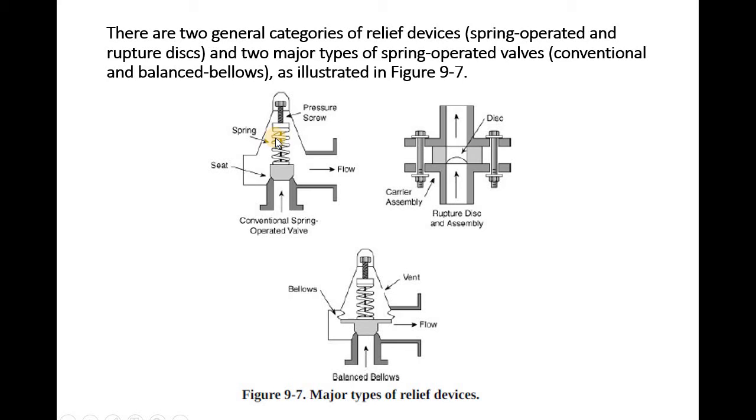And by the way, if you think of it, will this spring change its properties with time? Does it change with time or not? Of course it will change with time. Any material changes with time. Every person gets old, even screws get old, even springs get old, right? So these things are also like any material, it will get old. And of course that means you sometimes need to add screwing, just to make sure that the set pressure is always right. So this is what you have here, but that is a conventional spring operated valve.